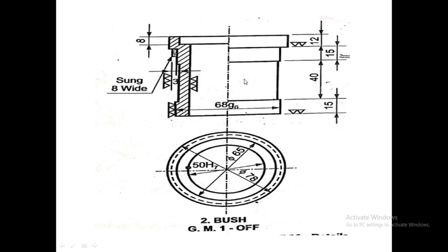It means that this diameter is coinciding with some other diameter that is visible from the top view. Again I am repeating that no hidden circle is drawn for this cylindrical part, although it is not visible from the top. So it means that this diameter is coinciding with some other diameter of the same dimension. And if we observe carefully, then we can conclude that the diameter of this part will be equal to 65 mm. So this hole which is of diameter 65 mm has the same diameter as this part. So this part will also have diameter 65.